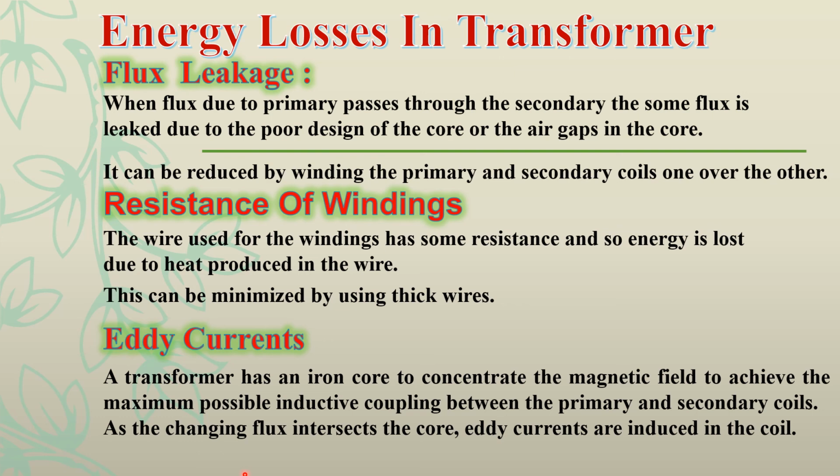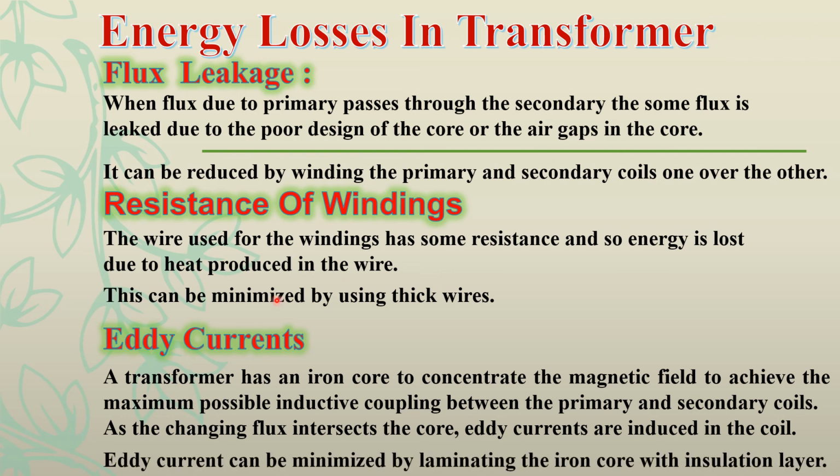So to minimize the eddy currents, we can use laminated iron, in which sheets of iron are separated by thin insulating layers. Eddy currents can be minimized by laminating the iron core with an insulation layer.